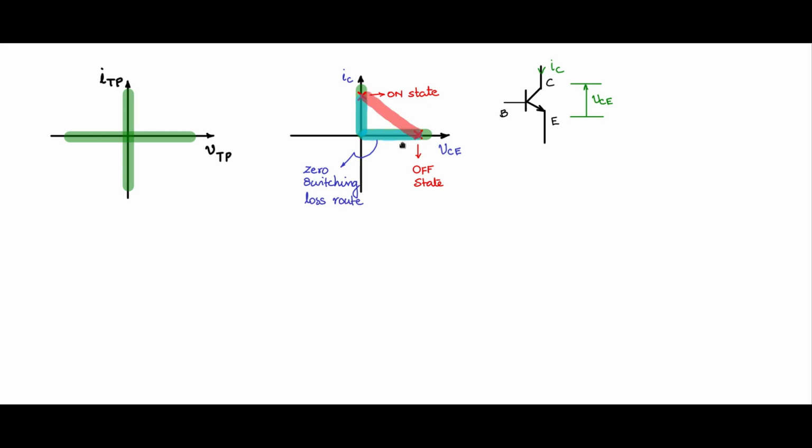So which basically means that if I am switching with 0 voltage and 0 current, then you have zero switching losses. On the other hand, the practical switches try to reach the other state directly, crossing through the linear region. So when you cross through the linear region, there are finite voltages and current in between, and there will be loss in the device.